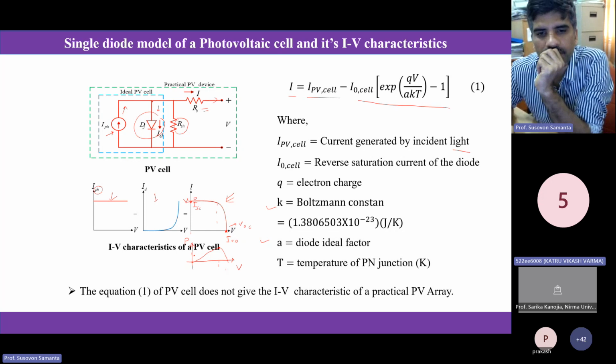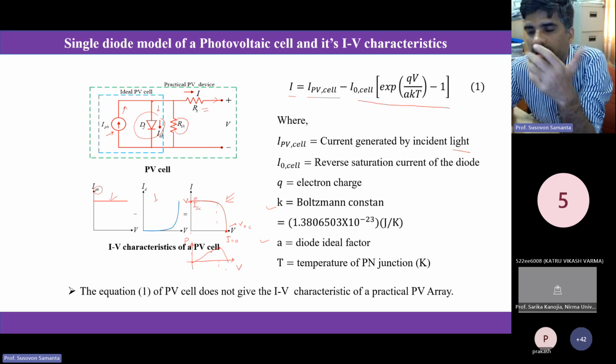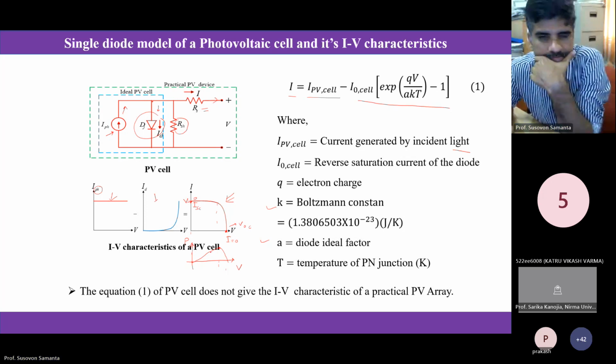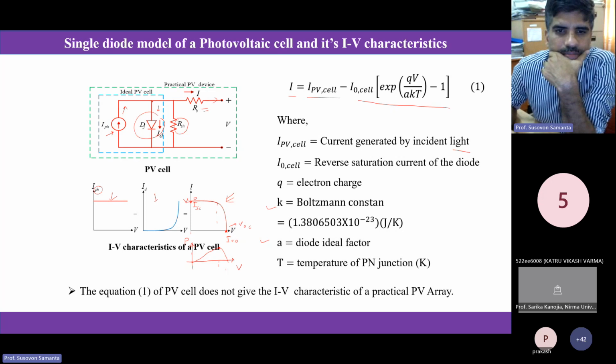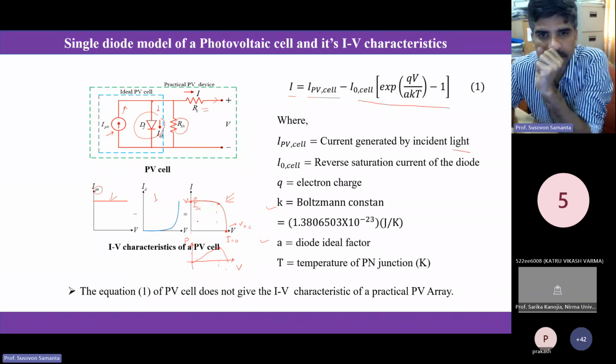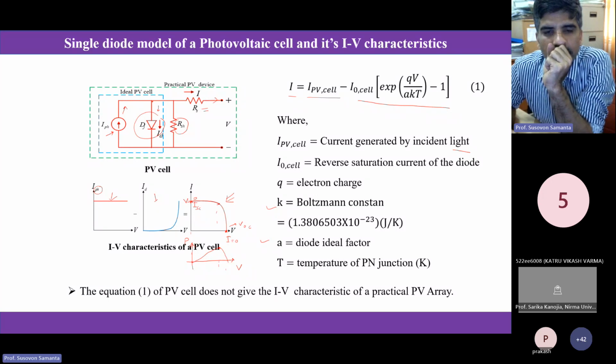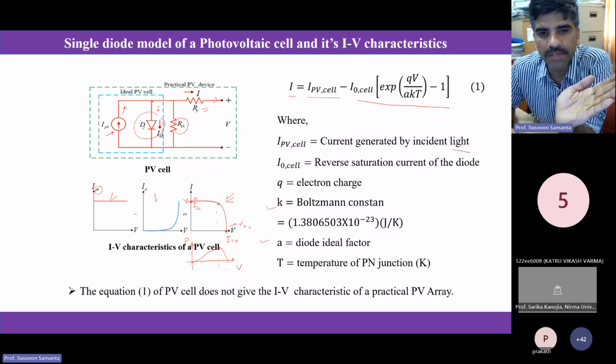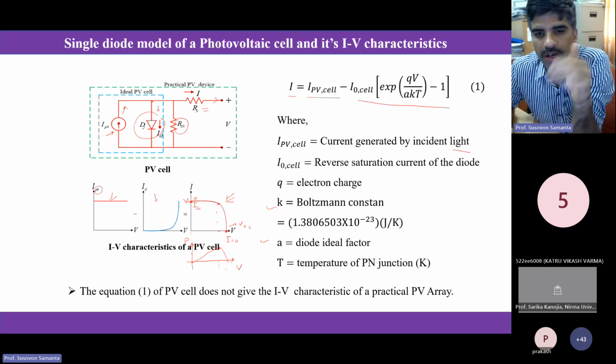Ultimately what we want is for the panel voltage to be at this point always if I want MPPT. So this is the important point from where we get the maximum power. This is the point where you have the short circuit current and voltage is 0. And at this point, current is 0 and you have the open circuit voltage.